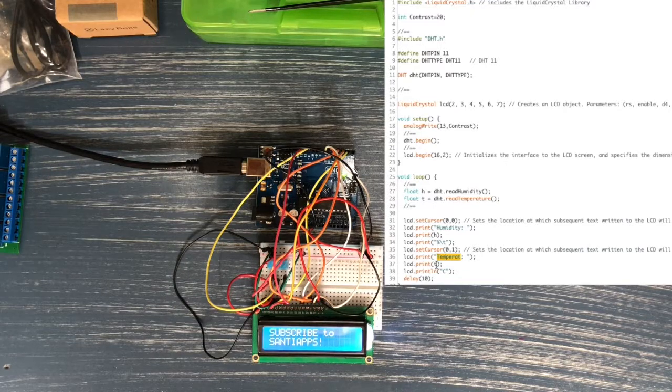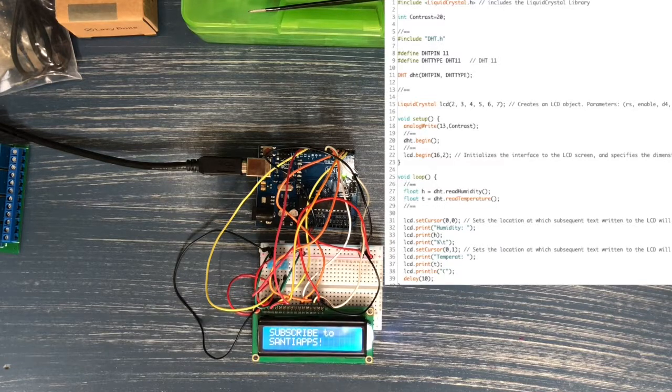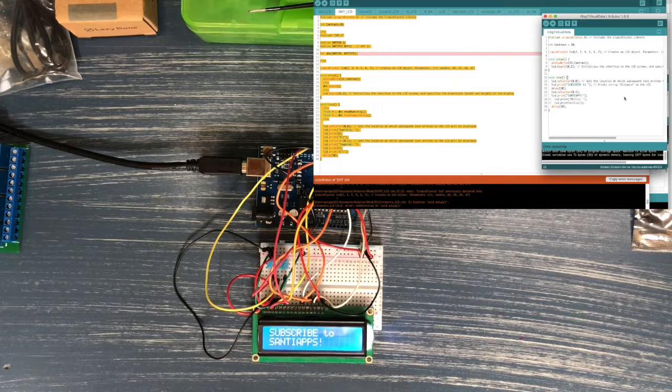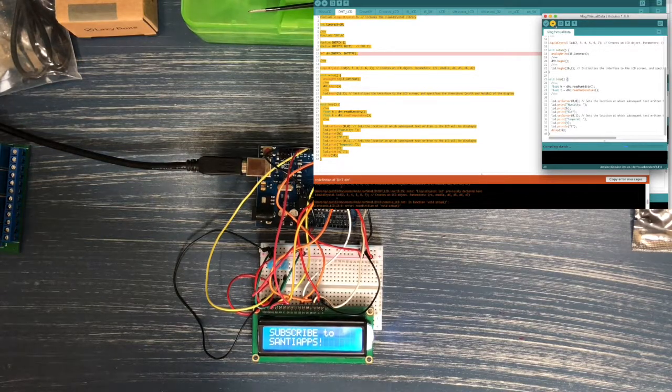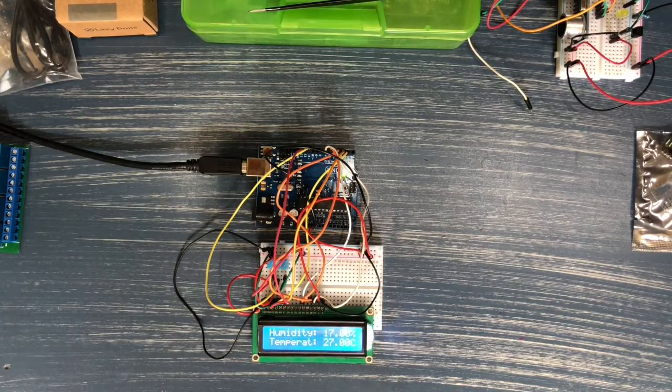All right, so the code looks good. Let's go ahead and select the code, copy and paste it in the sketch window that I said we were going to use, which is this one. And now we can click on Upload. Okay, perfect. So there it goes. And as it writes to the MCU, the screen is going to blink. And here is our data. Voila, humidity and temperature right there.